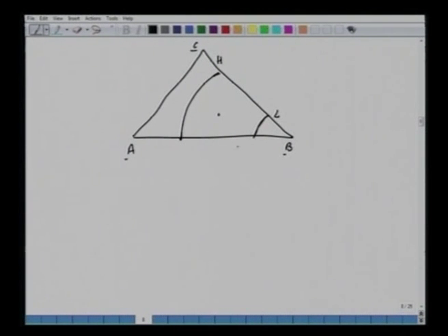Allow them to settle, and there will be a separation. Tie line represents equilibrium, so there will be a tie line. This phase we call R, raffinate. This phase we call extract, say E.